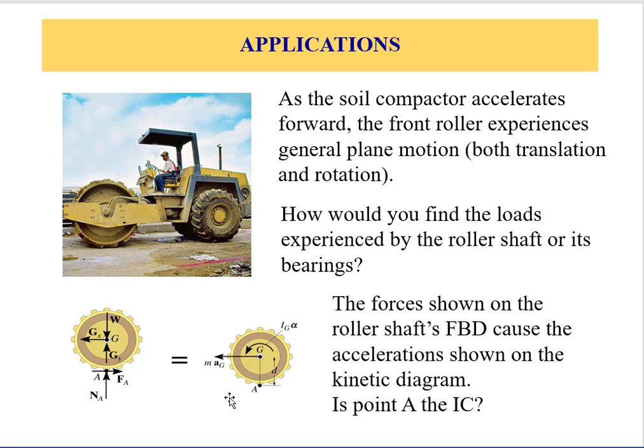Personally, I attach the coordinate system along the inertias. For example, I would deal with m a_G to the left as positive, and in this case I also use counterclockwise to refer to a positive moment, where I dedicate that I_G alpha is counterclockwise and positive direction.